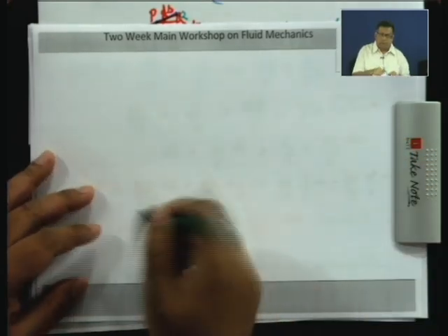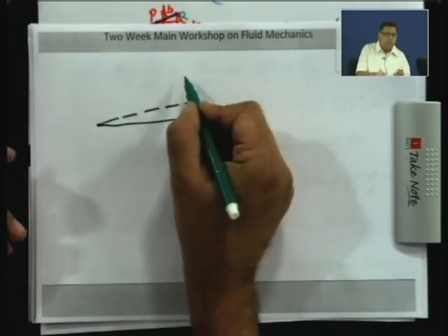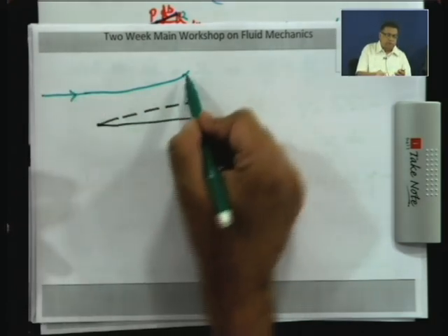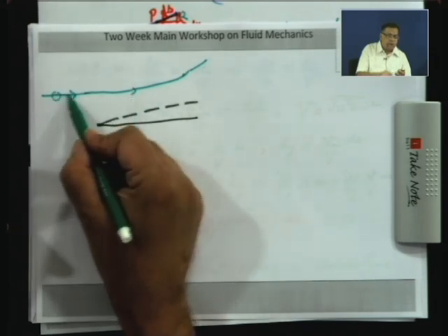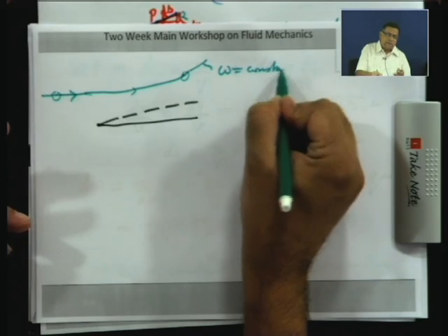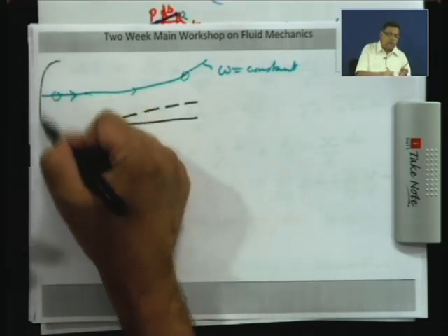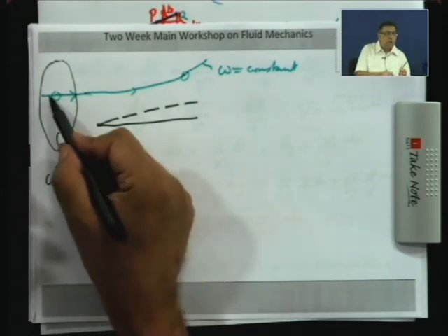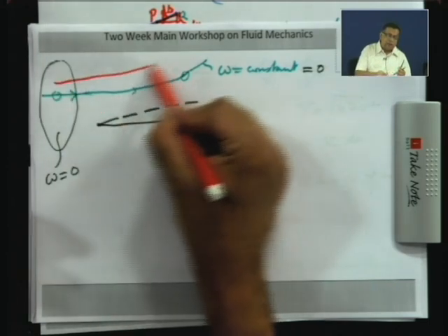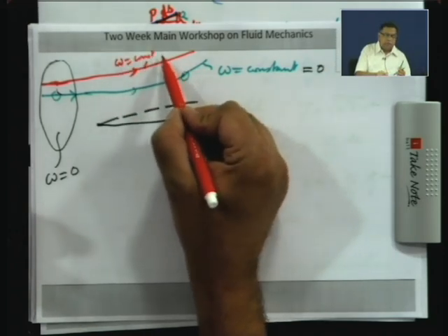Now, let us see what is the physical implication of this. I will draw the plate again and show the boundary layer over here, and you have a streamline which is going to be curved, and here it is going to be parallel to the x direction. So, this is a steady flow, the streamline and path line is the same. So, the fluid particle which is here is going to move along this and come over here and then move this way. Now, we are saying that omega is constant along this streamline, and upstream is a uniform flow where u is infinity not at one point, but at several points. So, we know that in this particular region over here omega is 0. So, that 0 value will be conserved and this constant will be equal to 0. So, if you have an upstream flow which is irrotational, you can take any streamline which is starting from this region with a 0 omega, again omega will be a constant over here and it will be 0.